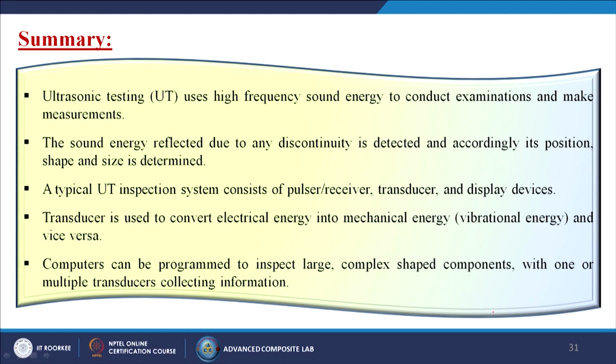So, now we have come to the last slide of this particular lecture. In summary, we can say that ultrasonic testing uses high frequency sound energy to conduct examinations and make measurements, which we have already gone through. The sound energy reflected due to any discontinuity is detected and accordingly its position, shape and size are determined. That also we have considered, how we can calculate and how we can get the information.